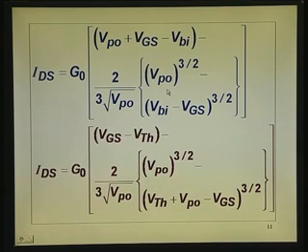So, all that we have done is we have substituted in that equation that we have been writing so far, that Vbi minus Vp0 is V threshold. So, here you can see Vgs minus V threshold, that is Vbi minus Vp0, that comes here, minus the same term Vp0 to the power 3 by 2.